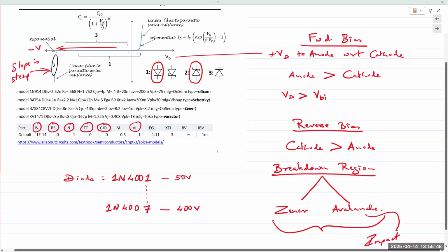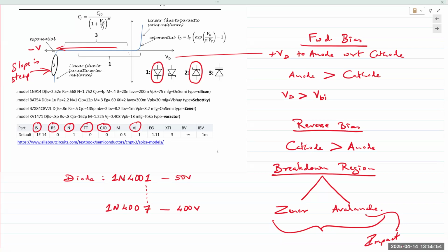If the whiskers on the cathode move inward, then it represents a Schottky diode. A Schottky diode is like any other diode, except that one end of the material is not semiconductor, it's actually metal. So you have a semiconductor joined with a metal material. And what this does is it results in a junction barrier potential of around 0.2 volts or less.